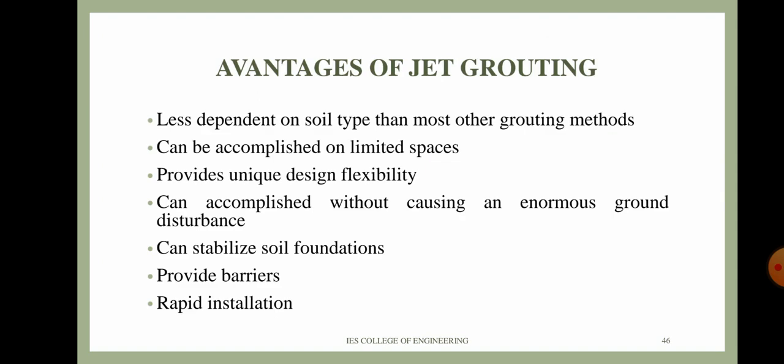And the advantages of jet grouting. First, it is less dependent on soil type. That is the main advantage of jet grouting over most other grouting methods. Jet grouting can be accomplished in limited spaces, and it provides unique design flexibility. It can be accomplished without causing enormous ground disturbance, can be used to stabilize soil foundations, provides a barrier, and follows a rapid installation method. Those are the main advantages of jet grouting.